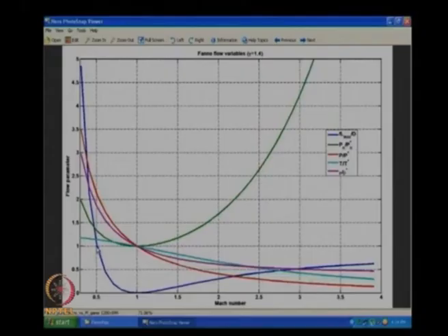So, what we are finding is, if my Mach number is, let us say, 0.5, it has some particular f L max by D, and if I fix my f and the D to be the same for two different comparisons, my L max is some particular value for this. Okay. If I go to some Mach number closer to 1, I find that the L max has become half, that is, in half that length it is going to be reaching M equal to 1.